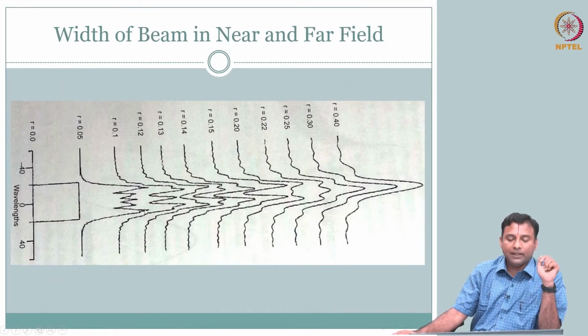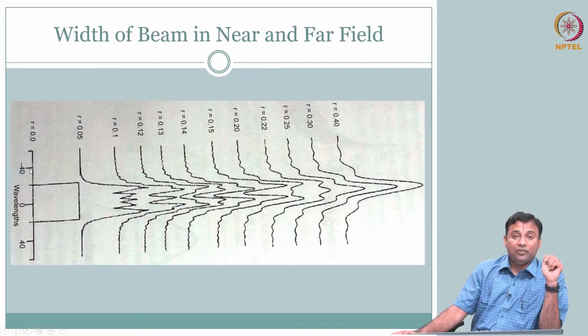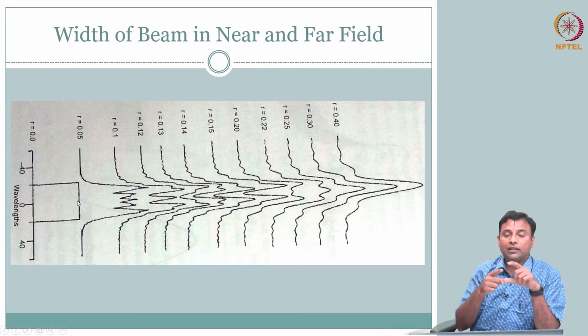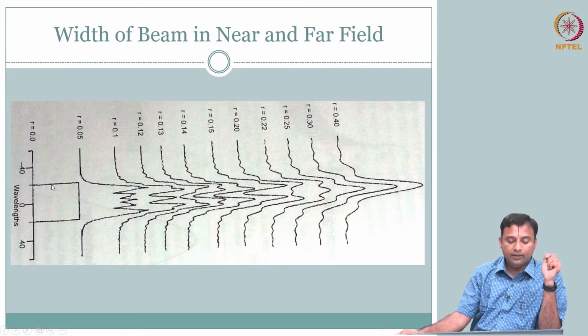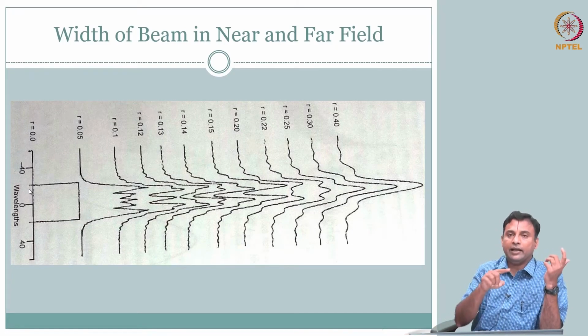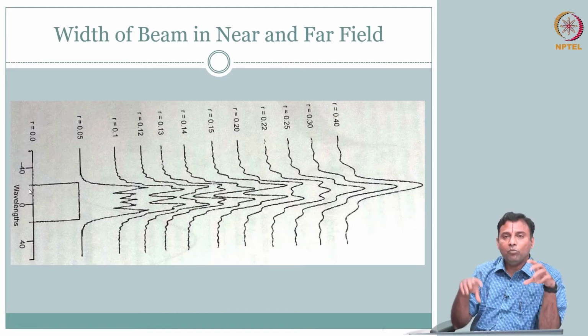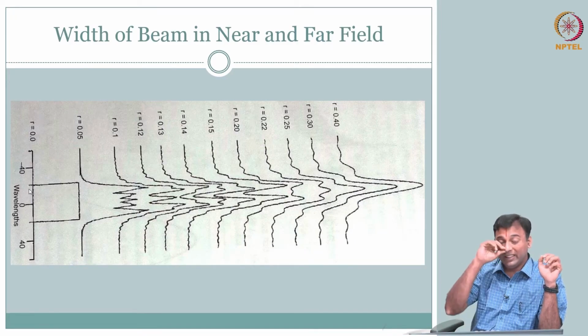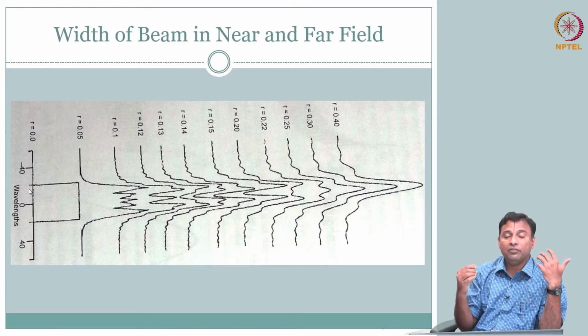One last aspect: if you have a rectangular transducer, think about taking one cross section. If you have a hard transition, it is very similar to the windowing concept that you know from your first level signal processing course, when you do filter design. If you take a rectangular window, you will have more ripples. So what do they do? They do some windowing, such as Hamming; you would have heard those terms.